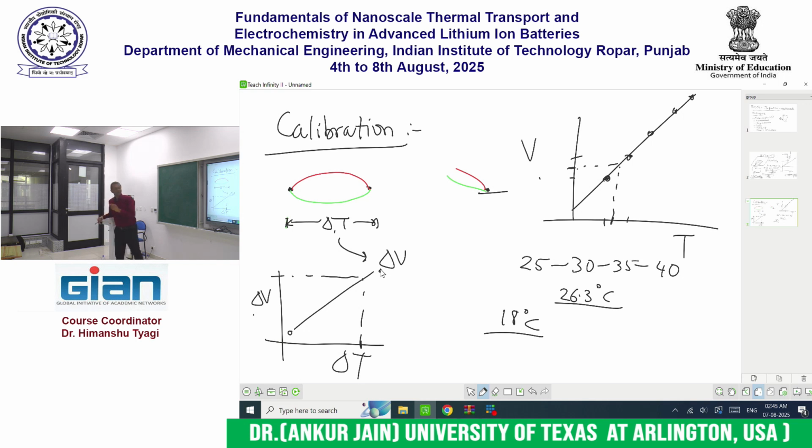If you have only 2 data points, even small errors in these 2 data points can cause your line to shift dramatically. Whereas if you have a large number of data points, then small changes in one of them do not really change your line dramatically. That is the reason why it is recommended to calibrate at a large number of data points before you finalize your calibration curve.